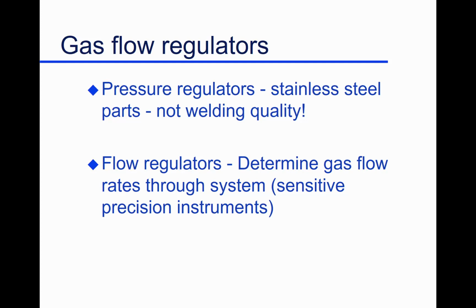So our pressure regulators, we have to control the pressure flow through this system, the volume of gas and the pressure on that gas. And we really have to have them clean too. Like I say, if we're going to detect as little as 10 to the minus 14th grams of things, we can't have dirty regulators. We can't have regulators with rubber rings inside of them or seals and this kind of thing. They're precision instruments, high purity, high quality parts that go into these regulators. And like I say, they are sensitive precision instruments.